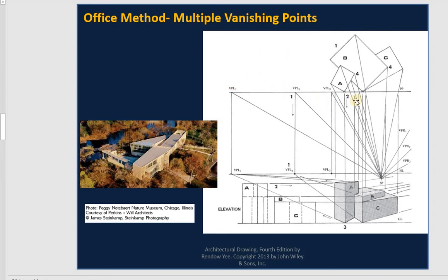Same thing on this side. You see this line and the line here is not parallel. So that's why you need to create vanishing point left 3, vanishing point left 2, and vanishing point left 1 right here. 1, 2, and 3, and after that drop down for each of them. When they cut on the horizontal line, you call that the vanishing point, and that's the one you can connect with the real dimension, which touches the picture plane, and you get the view from that one.